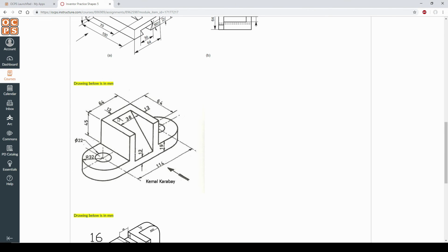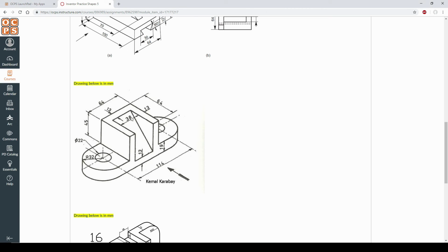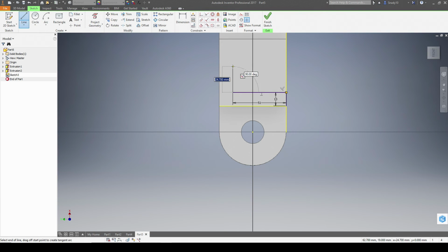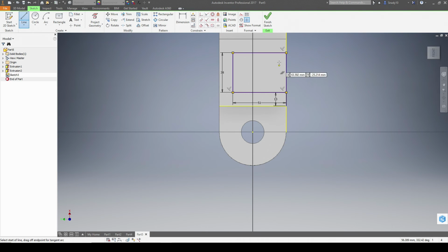And if you don't know the measurement for it, you just take the 64 minus the 13. And hopefully it goes the correct direction. If it doesn't, try it again. 64 minus 13 goes to 51. The width right here is 38. So set it to 38, hit enter, and then we'll go ahead and close this. And we're actually going to just close this portion right here because this is a part eventually that we will kind of cut down. And I kind of want to have that as a guide.